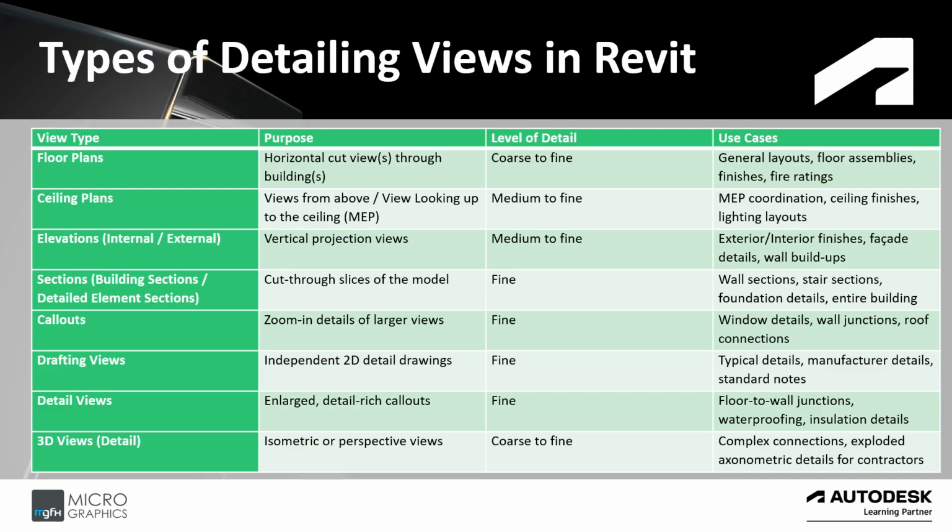Then you get elevations, internal elevations or external elevations. They are vertical projection views with medium to fine level detail, used for exterior and interior finishes, facade details, and wall build-ups.